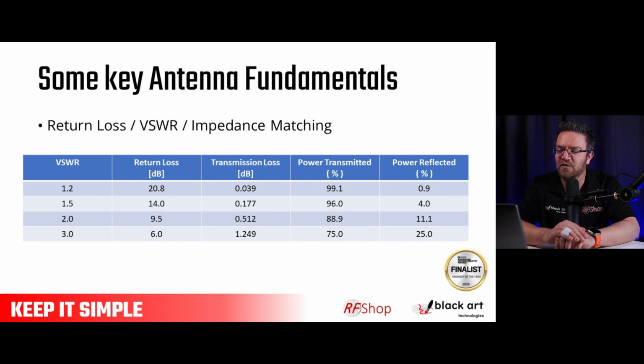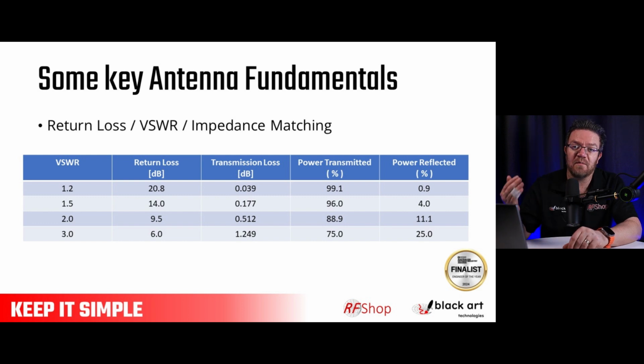But if you reach 2 to 1, often people say, yeah, you know what, this is getting close to the best we can achieve. So between a 1.5 and a 2 to 1, that is what normal antennas can do. If you look at the dishes that they use for the astronomy and so forth, definitely that's much better. 1.2 is almost absolute worst case, and then you go even better. So it is technically possible in the very high and very specialist to go way better than 1.2 to 1 as well.